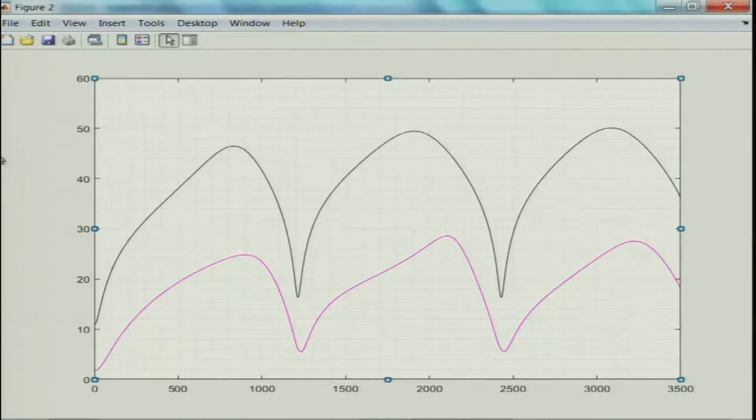We saw, if you recall, if you play back your last lectures at your leisure time, you will see that we used a variety of different perforate impedance expressions, and we did not quite see much of a difference, even when the flow was about 0.15, 0.12 or something like that. We did not quite see much of a difference.